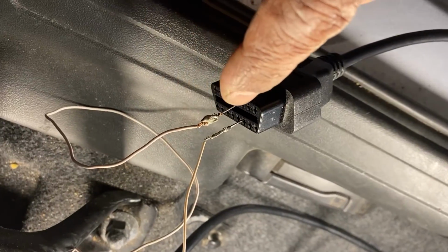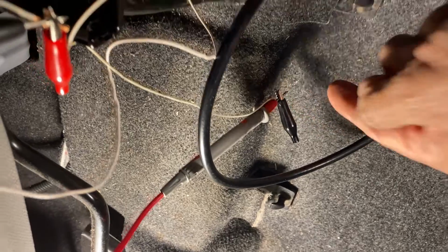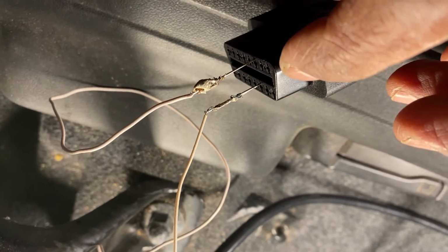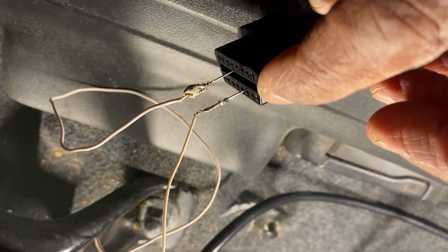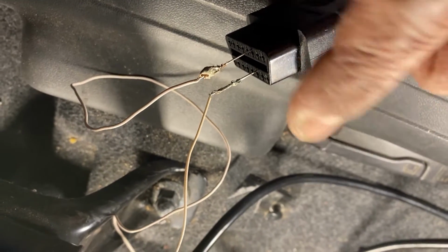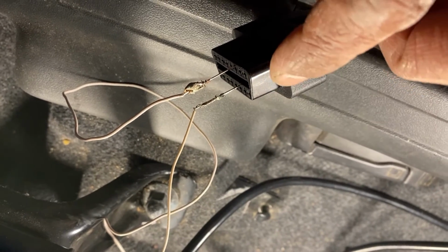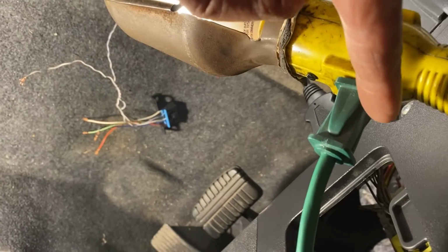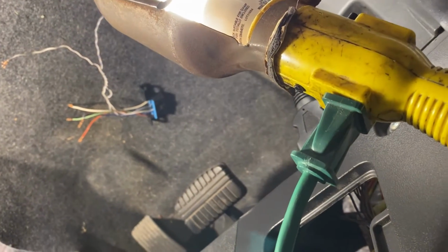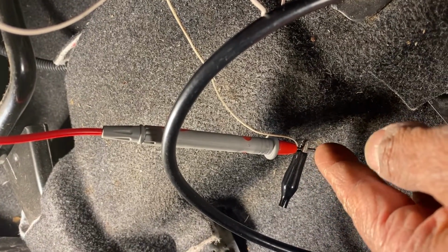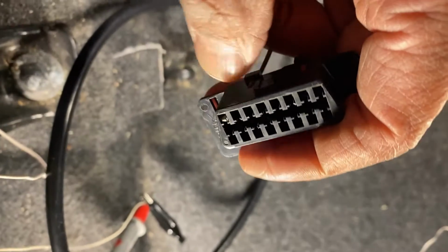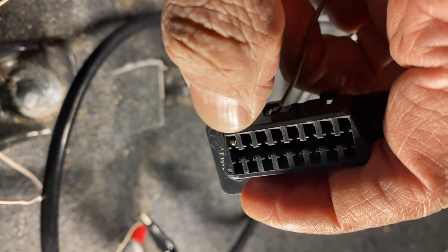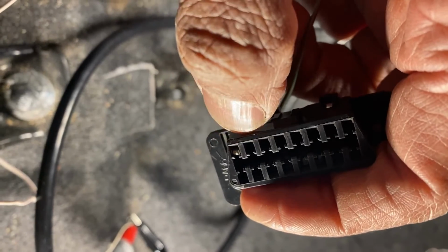Also be careful when you do this test, never stick the multimeter probe inside over here. Otherwise, when you try to use this port again, you're not going to have communication with OBD. When I do this, I prefer to damage my connection, not the board of the car. Some people make a big mistake when they get a stick probe for the multimeter and stick it inside the OBD, which makes the pin a little bit bigger. Then any time you have a scan tool, you're not going to have communication. So be careful with this.